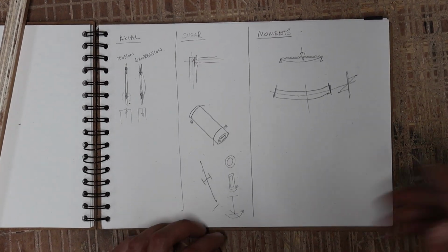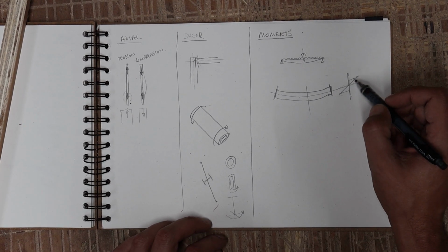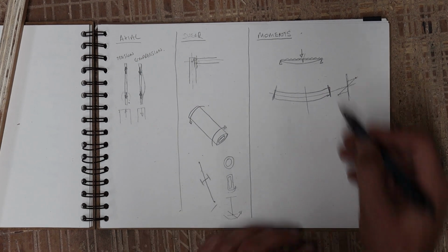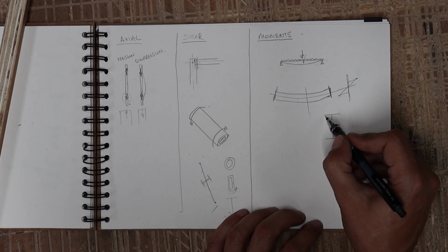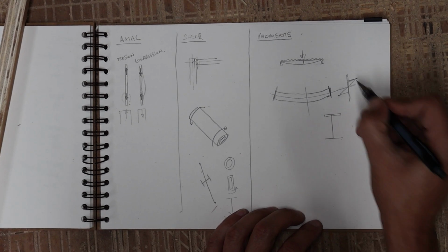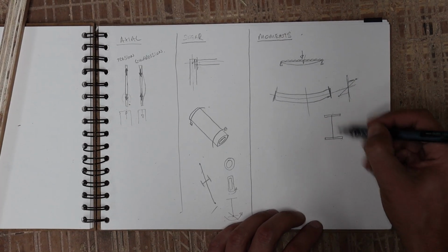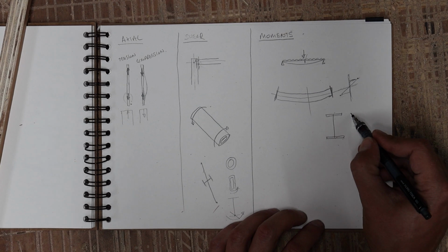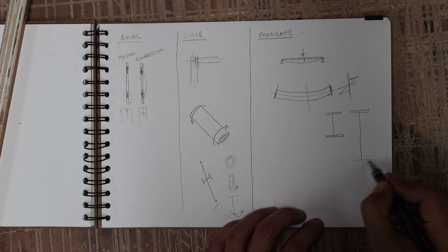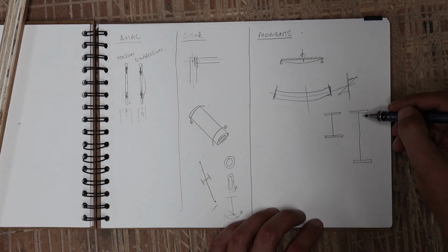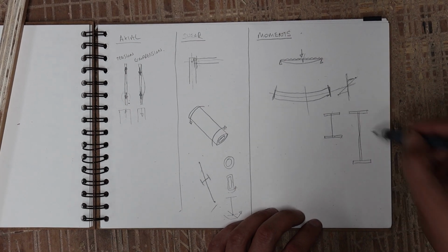Now for bending moments, this is a consequence of this action here that I was talking about earlier, where we have high forces at each extremity, and that's how you end up with an I-beam shape, because you want all of the material to be dealing with this peak of the force. That's what's doing all of the work. You get a real benefit from having depth. If you double the depth, let's just draw a beam that's double the depth, that's actually quite a big step up in beam terms. You probably get somewhere between 4 and 6 times the strength for the same I-beam.